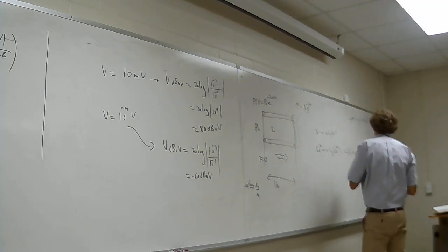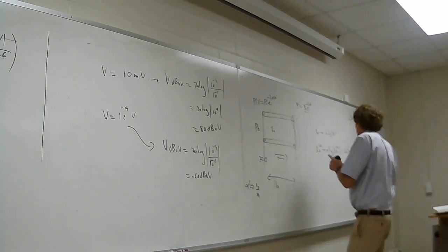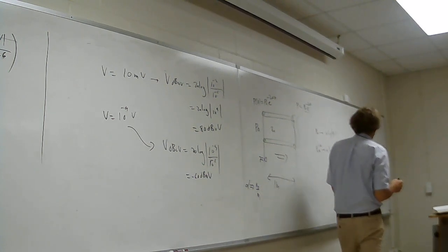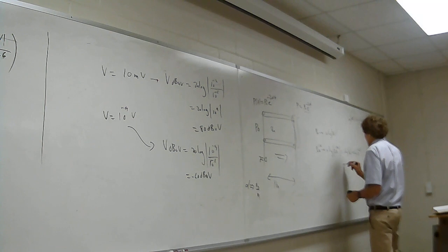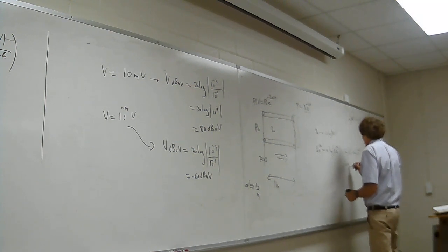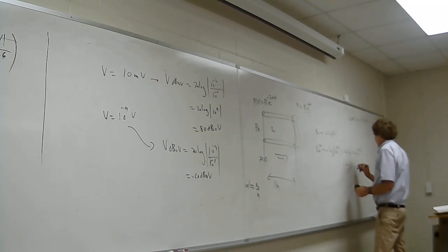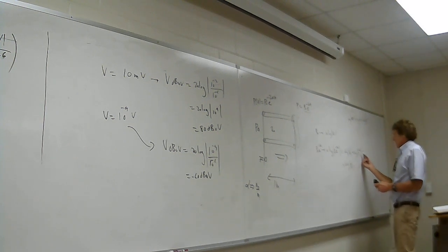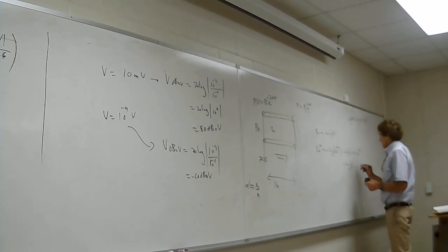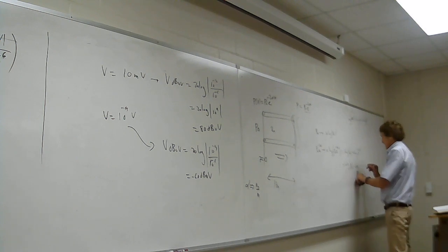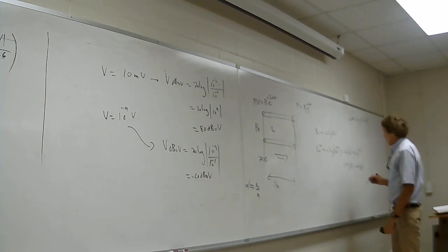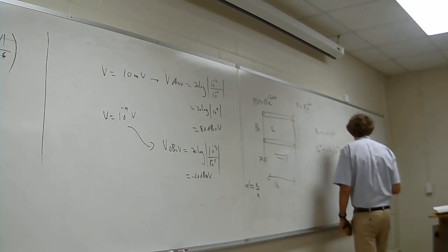Right, now take a look at this. So I started with P0 log of that. I ended up with this. I'll expand this further. This is 10 log of P0 minus, now take a look at this. I got minus 2 alpha. Well, anytime I have a log of A to the B, I can just take B out front. So it's minus 20 alpha right there times log, and this is going to be a log base 10 of e here, would be the amount of power loss in dB.